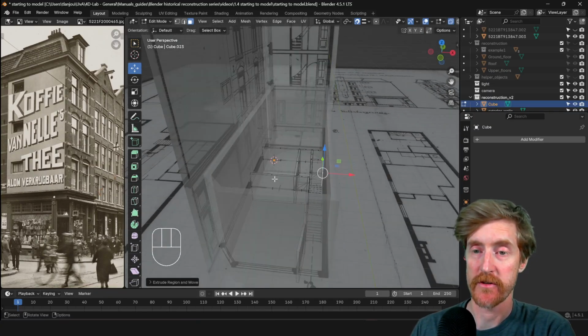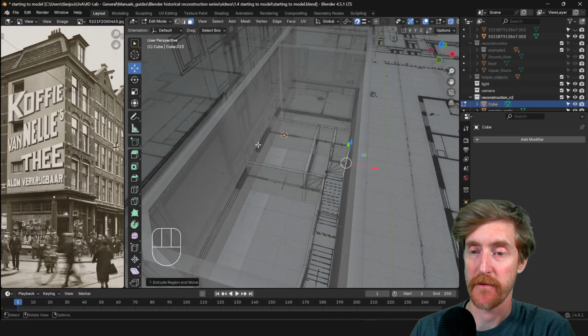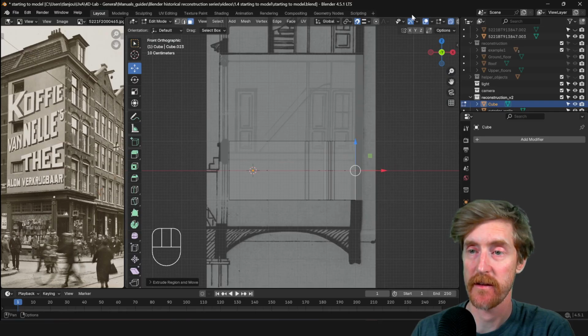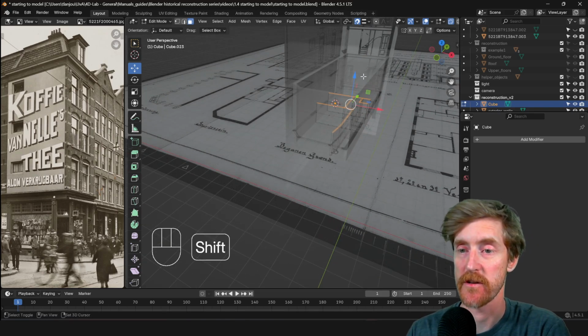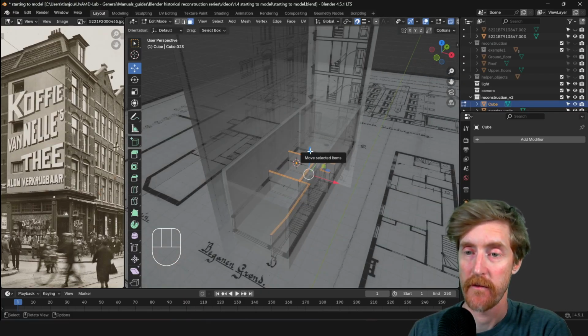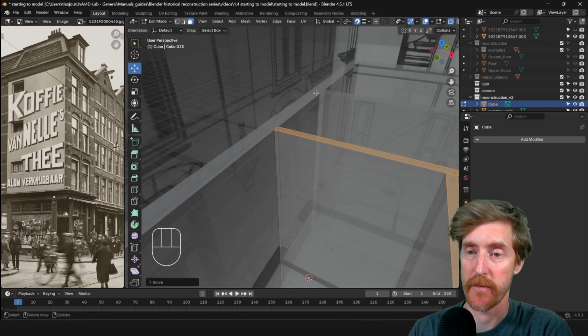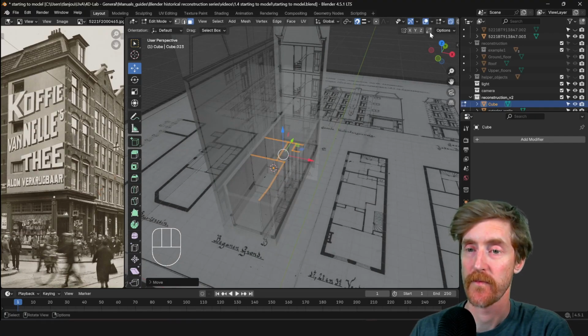So I want to move the top sides to align with the top sides of the exterior walls. There's a fast way to select all these, and that's to go into a side perspective, and with X-ray on I drag and select over the top of the walls, and then all the top faces are automatically selected thanks to the transparency in the selection, and then I will move them up and use snapping to make sure that they exactly align with the top of the exterior walls.